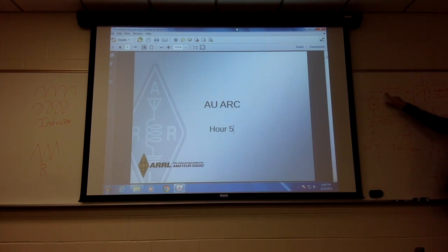Now we've got our single pole double throw, and now, no matter which you toggle, the light will always go on or off, vice versa. So here we've got one current path with both switches in the up position, and that would be on. Now it's off. Now flip the other one, and it's on. That's how that works.